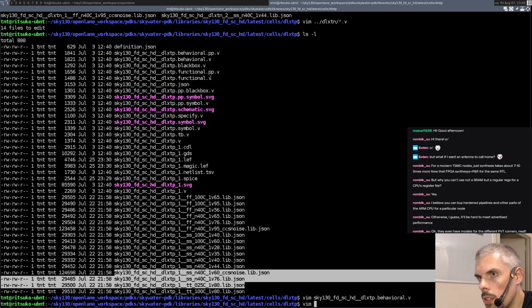But you don't have Verilog models that use the timing information. None of the Verilog models delay, and that's why I'm not sure I can actually use them to simulate this. With two latches following each other, you need to simulate the delay, because otherwise I think the simulation is just not going to work, right? You kind of count on the small delay for things to work. But that's something I could manually add myself, like slightly delay the clock of one of the latches for simulation or something like that.